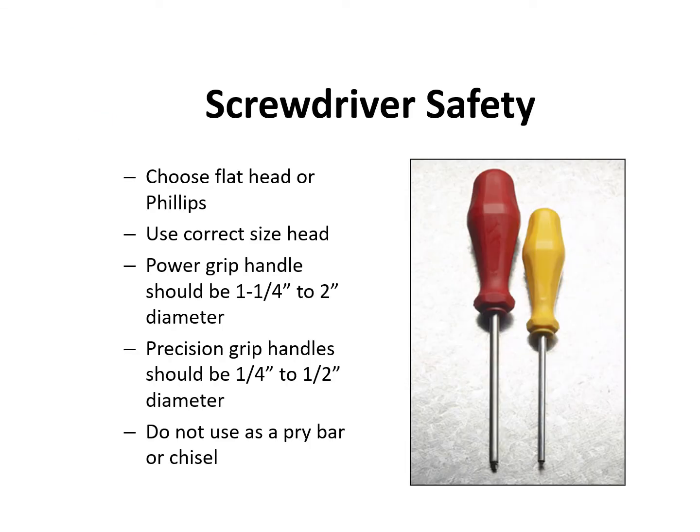When using a screwdriver, select the right type of screwdriver head for the task. Do not try to use a flat head to turn a Phillips head screw. Select the right size head screwdriver for the task. The head should fit perfectly into the screw head.